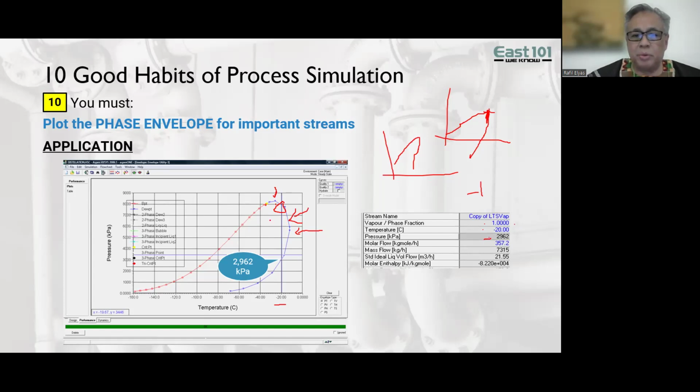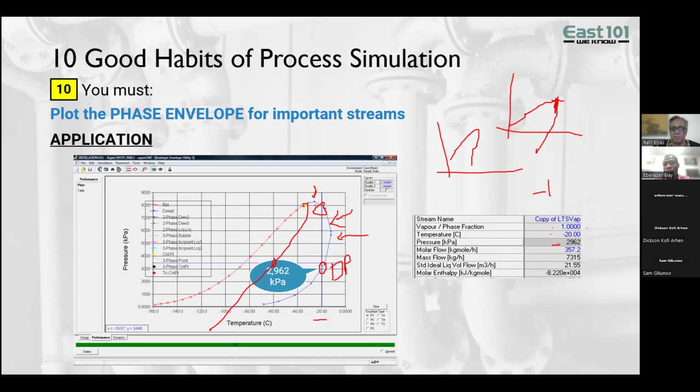Normally it might just look like something like this, and you might just have a single dew point. But because of this bulge, you have a dew point here and a dew point here. So this is generally called the dew point. And this second dew point, which arises because of the bulge, because of the decoupling of the maxima into a pressure and temperature maxima, is referred to as the retrograde dew point. So you have two dew points.